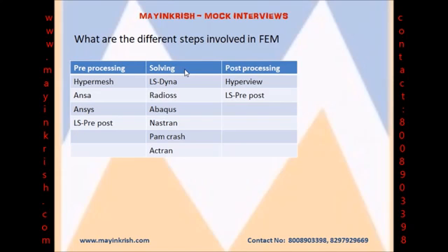Based upon the load vector, the software generates the external loads and applies displacement boundary conditions. Then the computer solves the massive matrix equation for the displacement vector, or whatever is the dependent variable in the problem. The constraint forces are also determined. The best solvers available in the market are LS Dyna, Radioss, Abaqus, Nastran, Pamcrash and Actran.